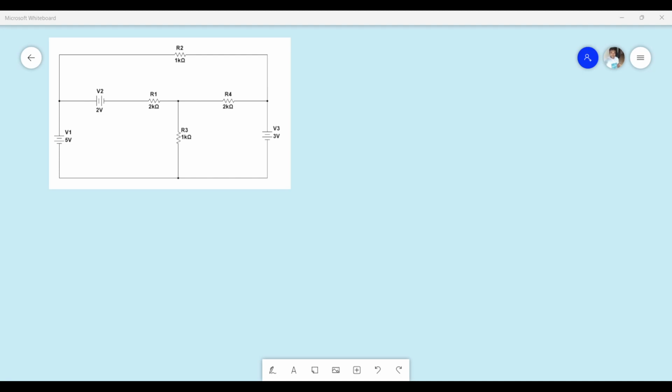So today we will be discussing mesh analysis, one of the basic analytic techniques used in network theory to calculate the individual mesh currents. Alright, what do we mean by a mesh? A mesh is a closed path where the current circulates and which doesn't have any other sub loops. It can have one loop inside which the current is flowing, and it cannot create any other subloops within it. Then we call that a mesh.